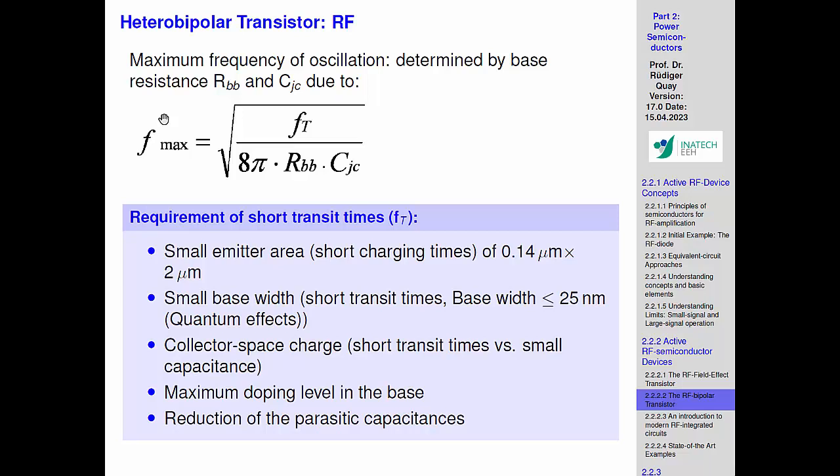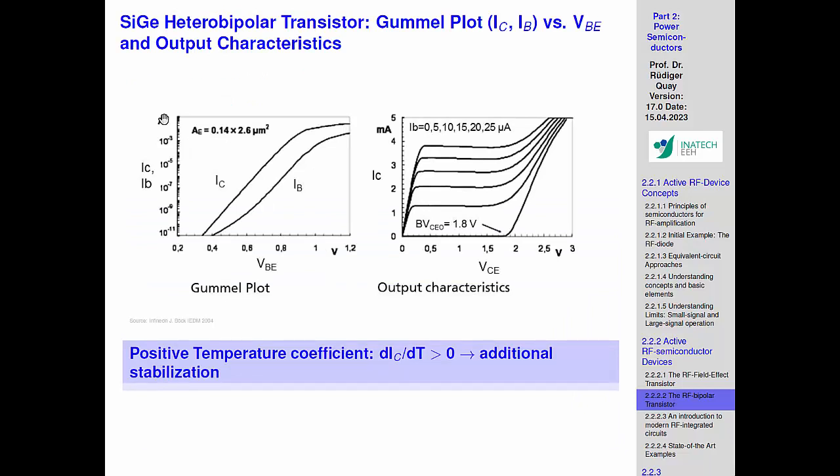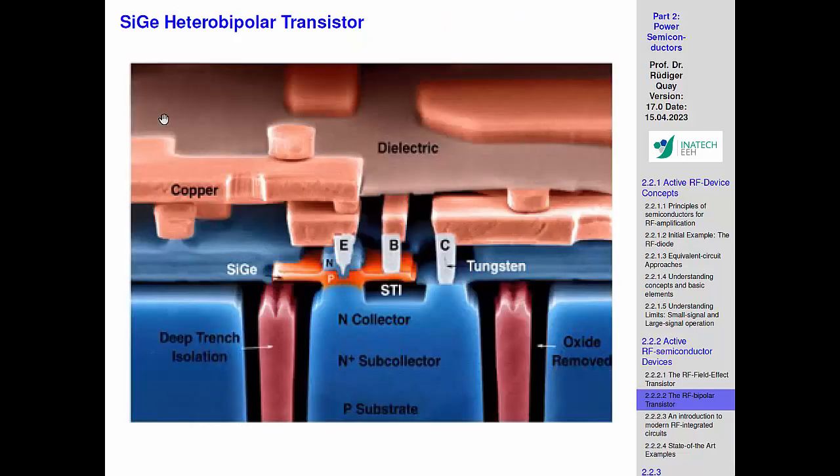So in order to reach the terahertz frequencies, we are primarily doing FETs only, right? No, the bipolars are also pretty good, they also get a bit more voltage gain, so it's a race. What it comes down to is always the engineering, how thin these layers can be.